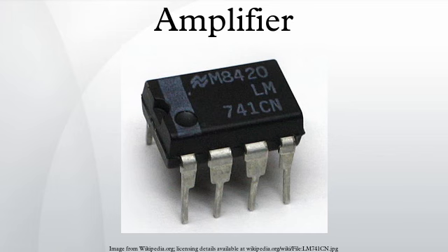An idealized op-amp has the following characteristics: infinite input impedance, 0 output impedance, infinite gain, 0 propagation delay. The performance of an op-amp with these characteristics is entirely defined by the components that form a negative feedback loop around it. The amplifier itself does not affect the output. All real-world op-amps fall short of the idealized specification above, but some modern components have remarkable performance and come close in some respects. Interstage coupling method.